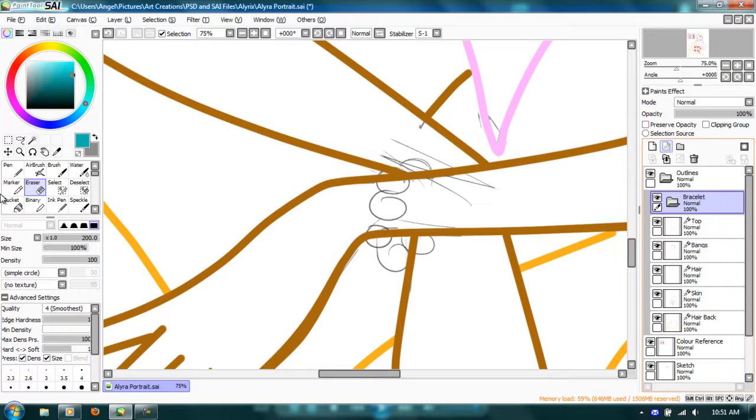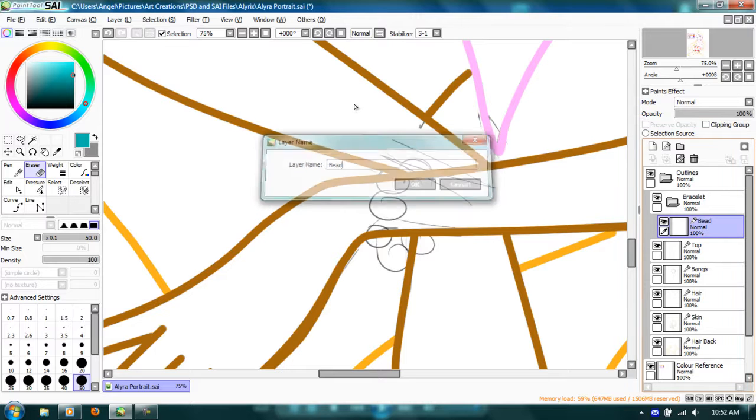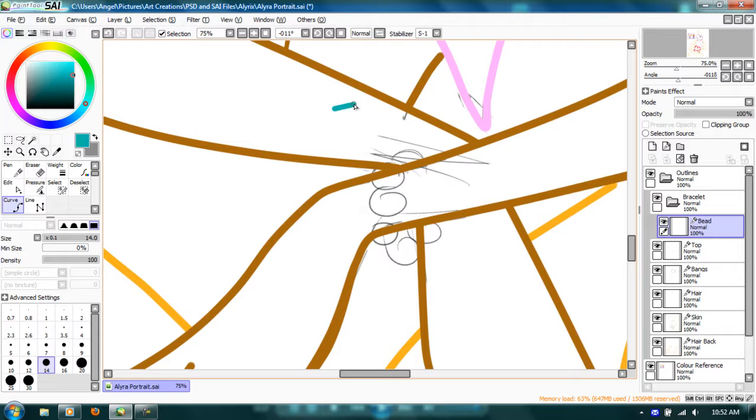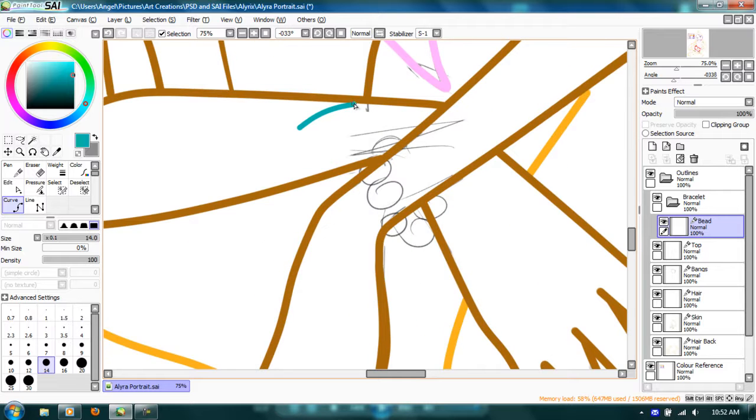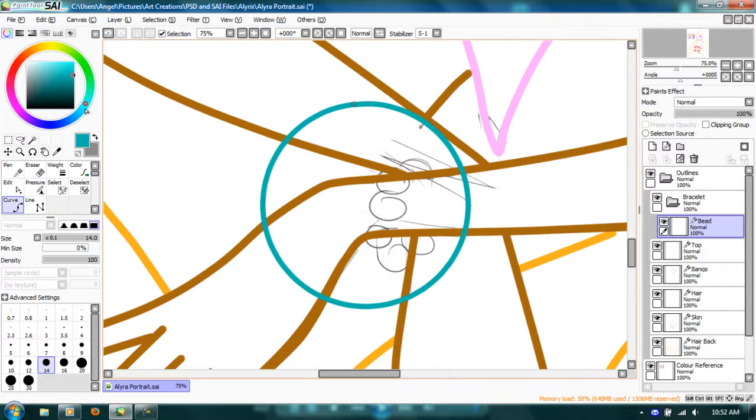Using the curve tool, click. Without moving your mouse, press Delete to rotate the canvas and click again. Keep pressing Delete and clicking until you have a circle, then finish your curve with Escape. Don't worry if your circle is too big, we will be using the Transform tool to resize it when we're done.